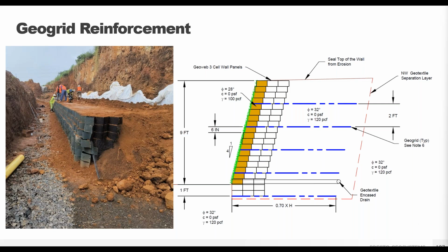The geogrids will need to be pre-tensioned once laid out. Install the grid as far forward as possible without sticking out of the wall face. Do not overlap the grid layers due to low friction angle and slip planes. And again, follow the geogrid manufacturer's guidelines.